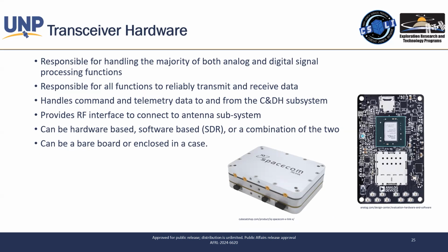A lot of what's actually on this isn't really software defined, right? It's an FPGA. It's more firmware, if you will. It's more reconfigurable hardware. The transceiver chip, you have no control over other than what filtering coefficients you send through it. They'll market things like that as software defined, but a pure software defined radio, in my opinion, is literally one that sends the IQ samples to your computer and you deal with it in a microprocessor architecture.